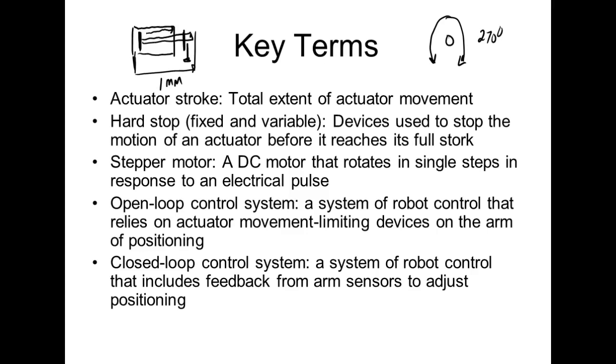Well, if you stall it, it's going to pull that same start current all the time. So what happens if we stall an electrical motor, most of the time, if we don't protect it, it's going to burn up. Fluids don't care to be stalled. So a lot of your robots that are programmed on hard stops are pneumatic or hydraulic robots.